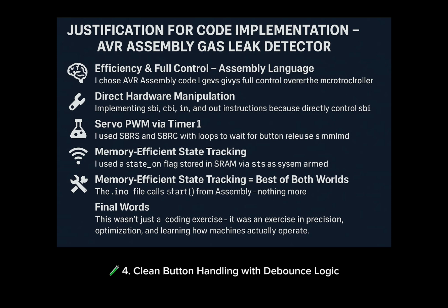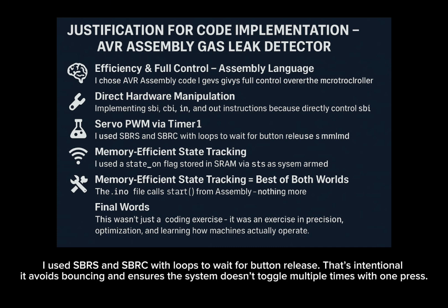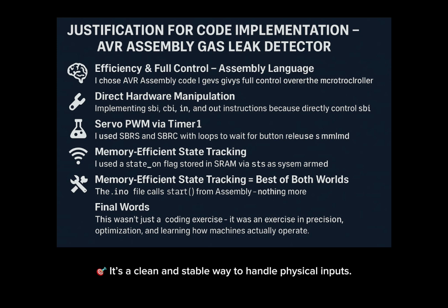4. Clean button handling with debounce logic. I used SBRS and SBRC with loops to wait for button release. That's intentional. It avoids bouncing and ensures the system doesn't toggle multiple times with one press. It's a clean and stable way to handle physical inputs.